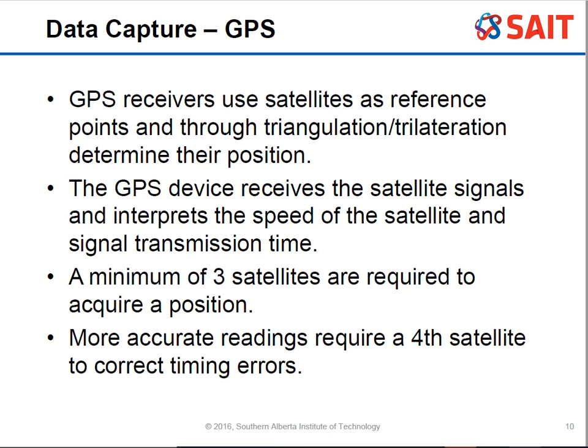And it will receive it, and we have something called a float versus a fixed position. With handheld GPSs, if it's bouncing around, it's in a float position. If it seems to be stabilized and just moving a little bit, then it is in a fixed position. That's because we have something called ambiguity. Again, that's a whole other class in GPS on how to use a GPS properly. But with a handheld GPS, you don't have to worry too much about it, because the accuracies are low anyway, so it's not the end of the world if it's kind of off.